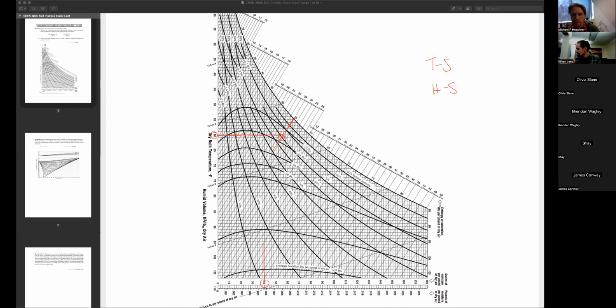When you say percent, you mean temperature, right? Hold on, let me say that again. So 60-degree dry bulb, 55-degree wet bulb would result in a relative humidity of 70%. Did I get that one right then? Yeah, that sounds better. I thought the line goes straight, and I'm probably wrong, but I'm just making sure.